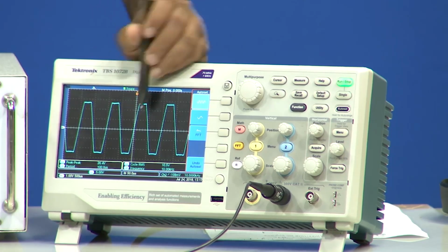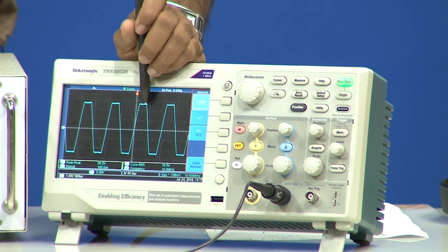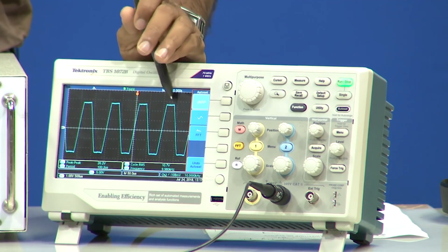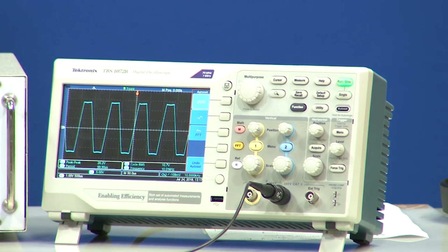Now you can see that the output has become clipped, it is trying to become like a triangular wave. So, this is not the desired output as per design. From this experiment, what you can see is that the range of the op amp is from 0 to around 12.5 to 13 volt peak to peak input, or 0 to 6 to 6.5 volt peak sinusoidal wave. By range of the op amp we mean the input signal range.